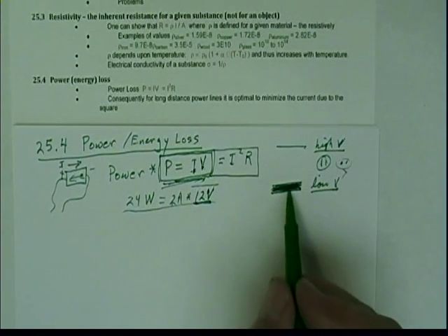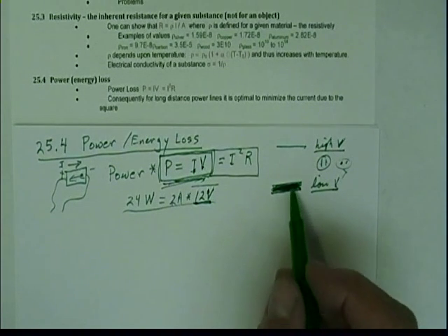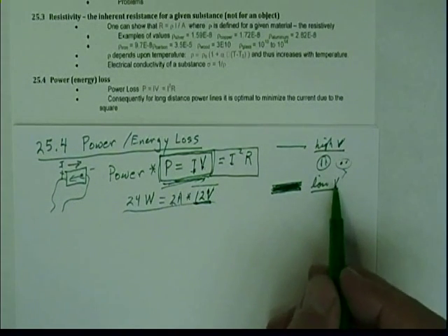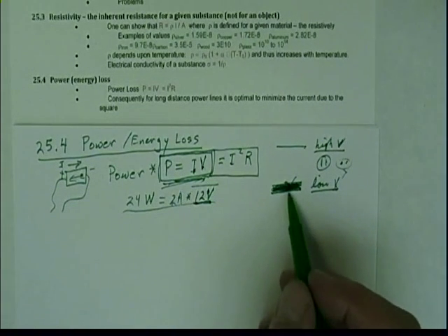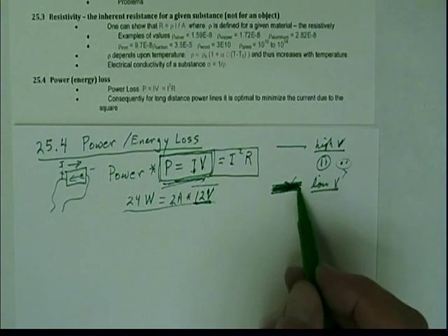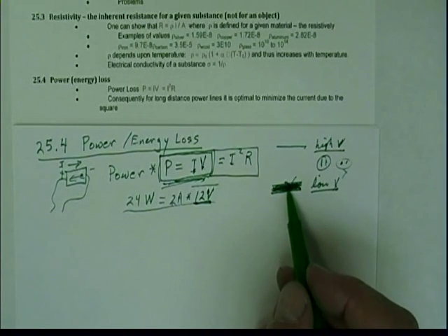And so this is a cost and an expense of keeping very large wires in your home, even though you have low voltage. These very large wires, if they were bent and bent and bent, can develop a crack in one side, and then they become very thin at one point. And if that happens, then in fact this can heat up a lot and it can burn your house down.